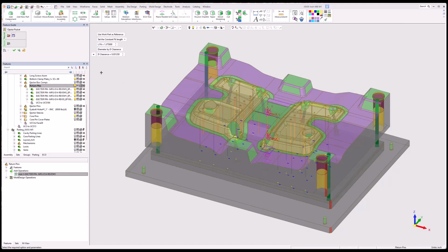So what I'm going to do is change my clearance here. I'm going to change my fit length to constant clearance length. And I'm going to kind of lie to it and give it the thickness of the original block, or maybe even slightly bigger than the original block. It comes up with an error. It says, I don't like what you're doing.